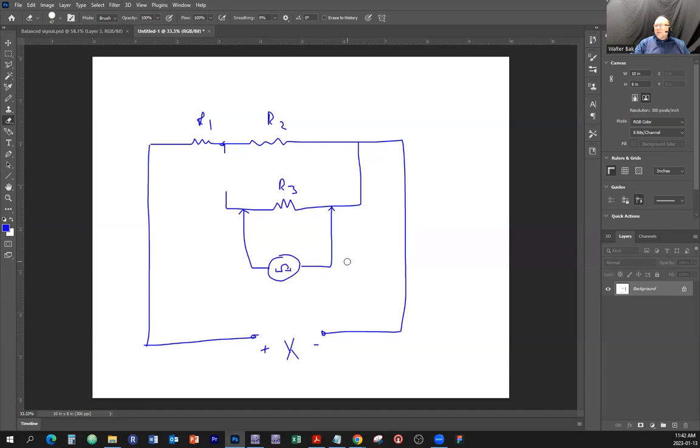That's why we not only need to remove the component, we also need to remove the power, because if we have the power applied and the component is not removed from the circuit, you're going to apply voltage to some voltage that already exists there. Not only are you going to get a false reading, you can actually damage either the circuit or the meter or both.